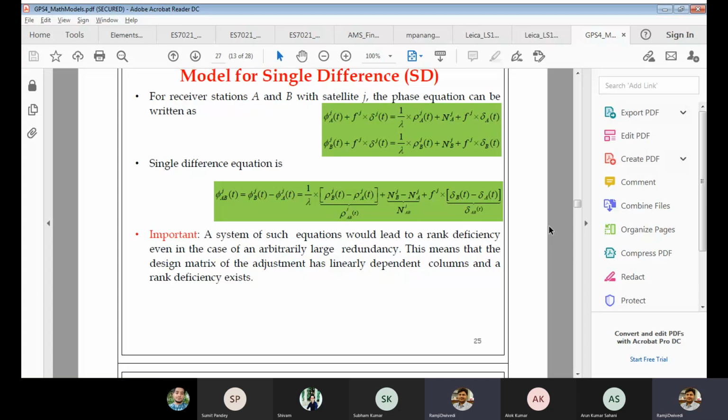So this concept of relative positioning is there to help you remove that minimum layer of error. Let's say you have a base station in Prayagraj and a rover station in Kanpur. This relative positioning won't work because there is a certain range of distance in which the errors considered to be correlated stay within a proper threshold for the baseline. So for 80 kilometers, 100 kilometers, you can fairly work with relative positioning. But for distances more than 200 kilometers, you need to incorporate models which can tackle these large distances, because ultimately our objective is to improve the precision, isn't it?